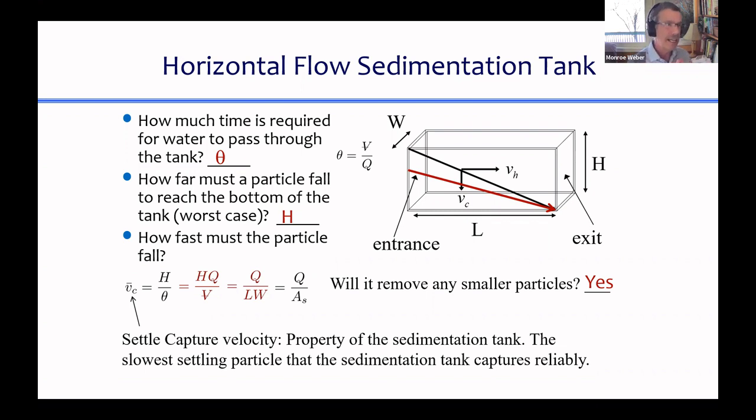See, Cornell University has a water treatment plant that was built in the 1920s, I believe, and it's still rolling along. And it's got a horizontal flow sedimentation tank. And that sedimentation tank is probably about 4 meters deep, like 12 feet deep. And during the course of the year, and especially when there's runoff in Fall Creek that they're using as their water source and the water is really turbid, that sedimentation tank begins to fill up.